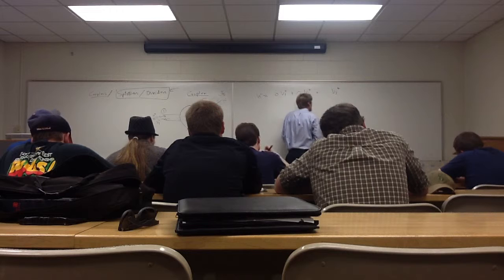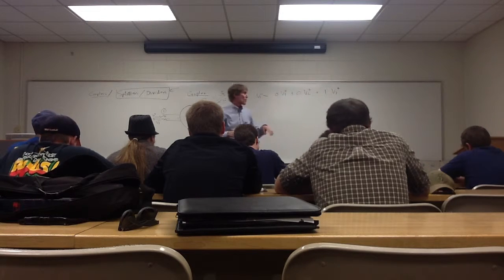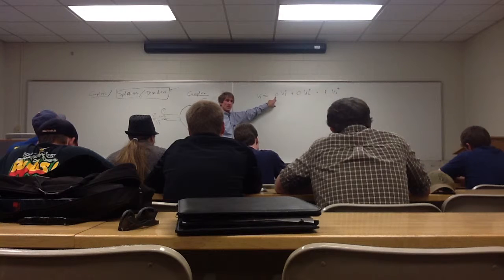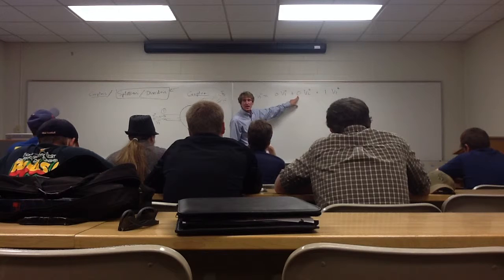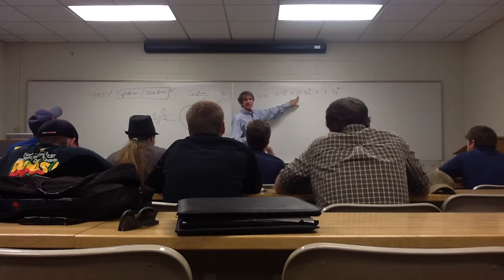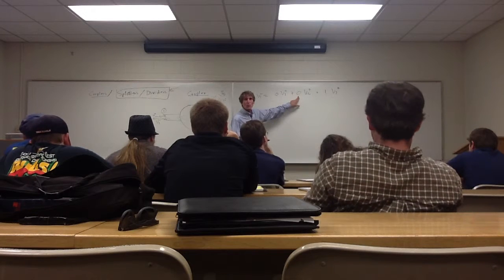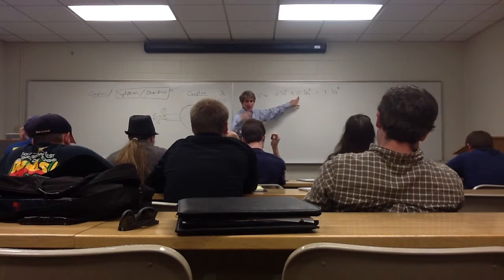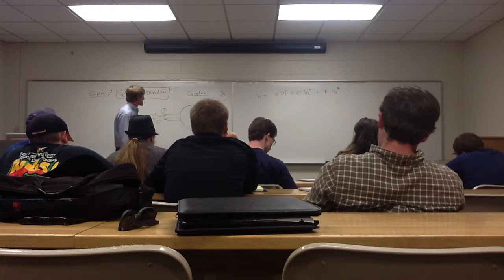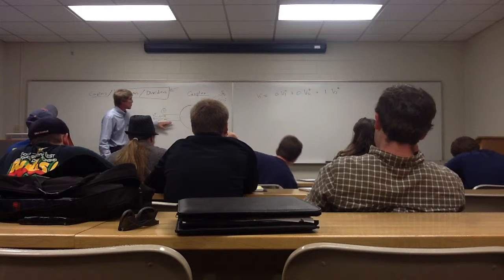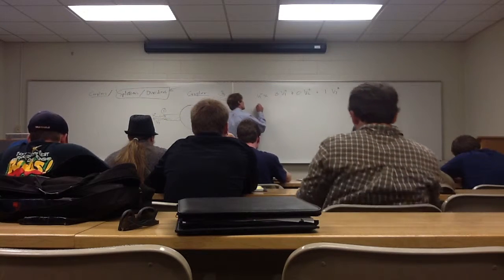Now this is ideal. You'll never get these values. What you're going to get is something like that. You'll probably have a very low value of a reflection coefficient. This would be a coupling coefficient, and this may be something that's, I don't know, 30 dB below what it should be. In other words, 1/1,000 of the signal gets out. Now, everybody can see that at least this fulfills the request that everything from port 3 comes out port 1. Does that make sense to everybody? Let's go down to the next one, V2.